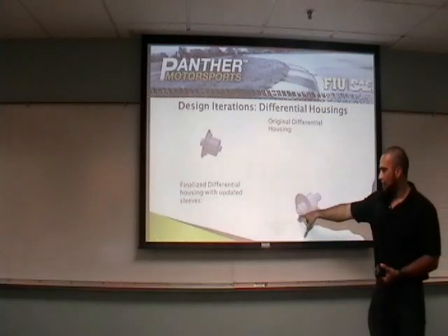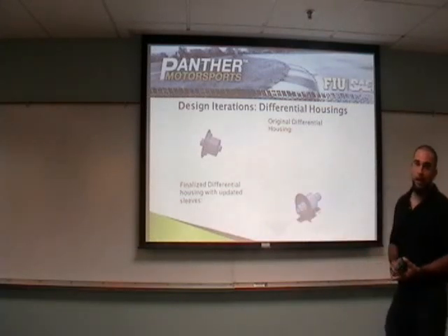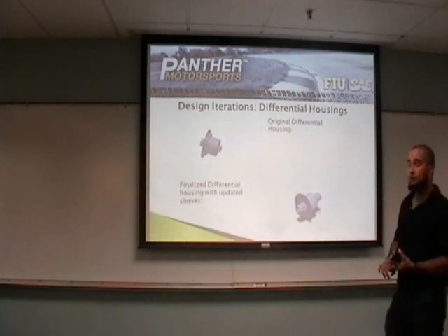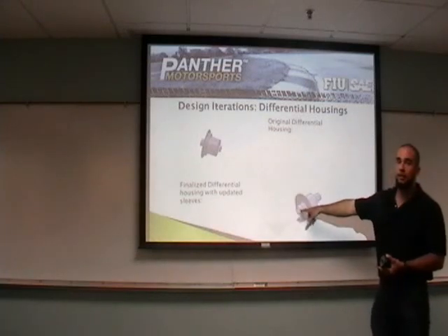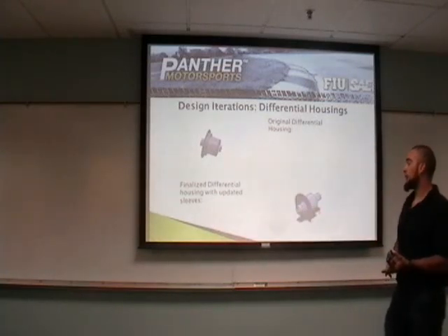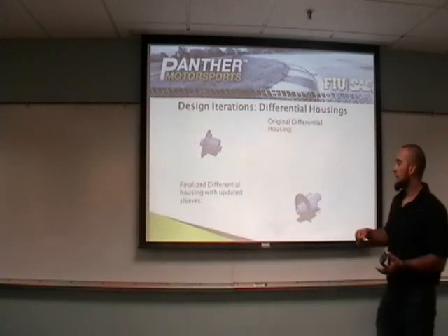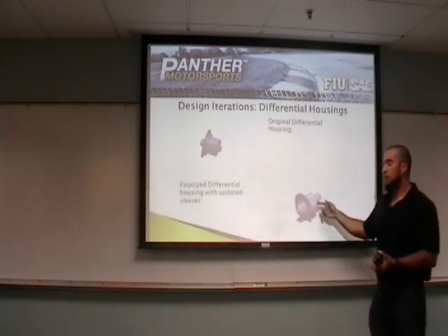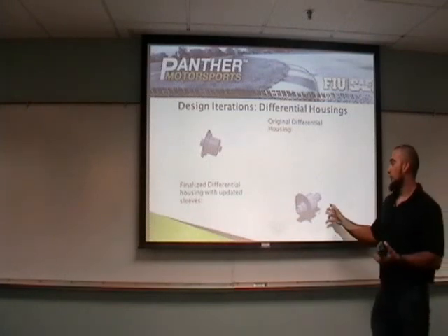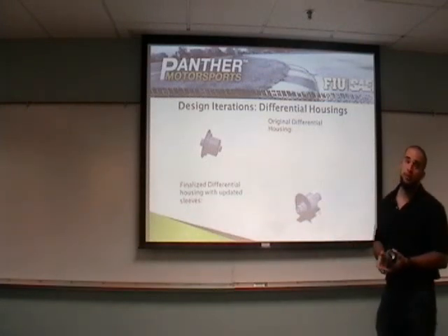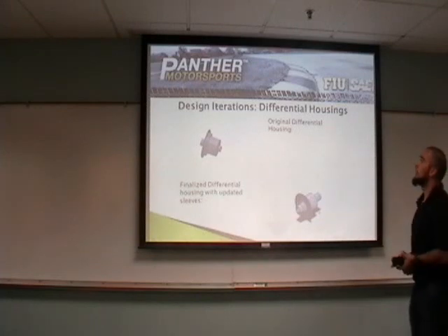Secondly, on the inside of the sleeves, there's actually a grease sleeve fitting that will be placed inside here to prevent oil leakage. Secondly, these two sleeves will allow the use of the same size diameter bearings, so no two different size bearings will be used, and this will also allow for simplicity of disassembly and assembly of the differential housing.